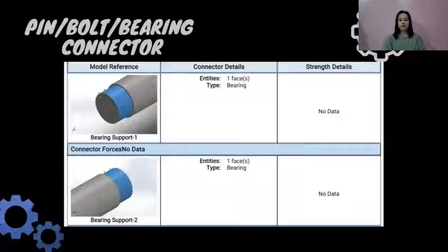in designing. So this part shows what type of support or fixture is used for the simulation of the shop model uneven desk, and that is bearing support. A bearing connector is a combination of spring elements that joins two concentric cylindrical parts and mimics the behavior of a real-life bearing, allowing for translation and/or rotation between the two parts.